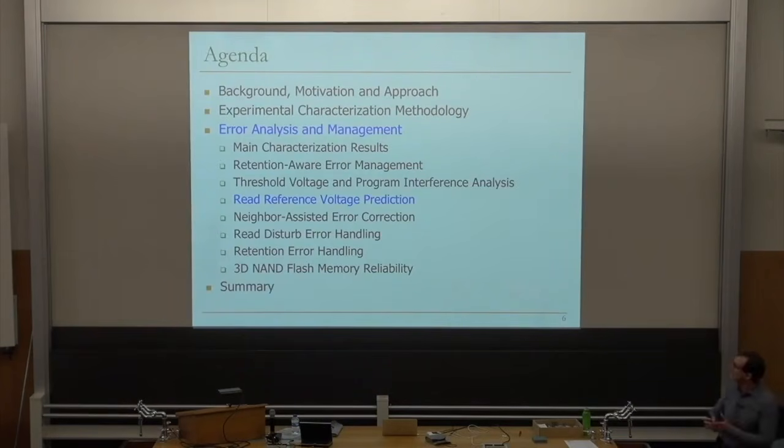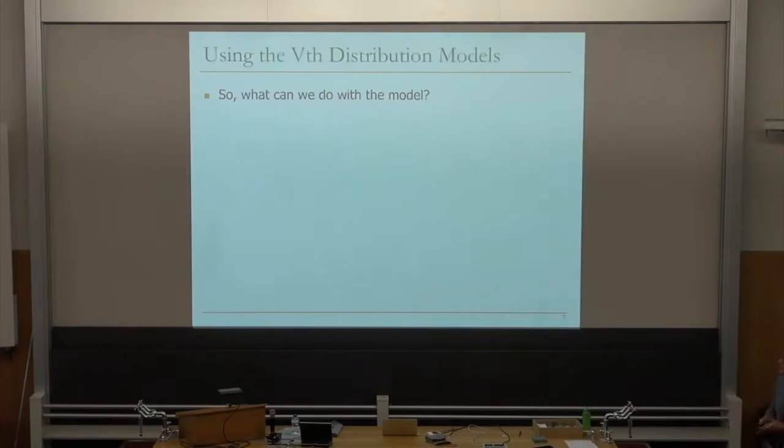Actually, we were discussing a lot of techniques that are implemented in flash controllers today. Contrast this discussion with the DRAM discussions that we had earlier, right? DRAM controllers are really doing nothing compared to flash controllers, if you think about it in terms of reliability, for sure. But basically everything that I'm going to discuss over here is pretty much implemented or is being implemented in flash controllers going forward. So read reference voltage prediction is something that definitely exists today.